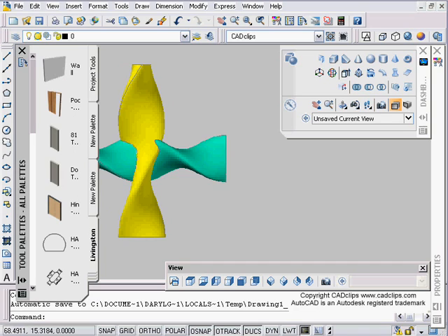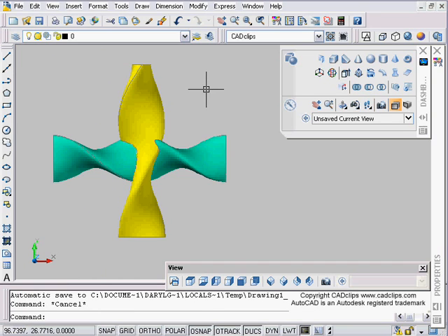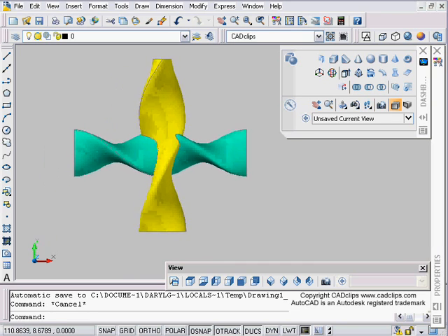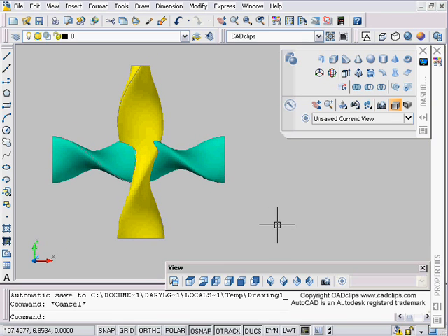And the sweep command is nothing new. The difference being it's a little bit different with interface, and you don't have to align the profile you're sweeping with the path. So that part has improved, which makes things so much easier for us trying to teach 3D because you're having to use your UCS a lot less now, and it's just become a lot easier and more intuitive.